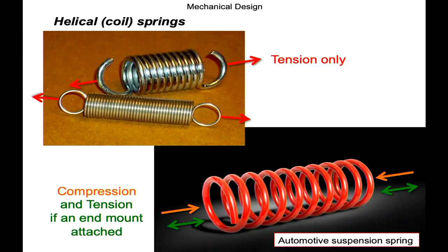We could expect something like that: there's going to be this little zone near the start of loading where those ends are going to have to take up the load. They'll deflect in a distinct way, and once they've deflected to a saturation point, then the main spring will take the load.